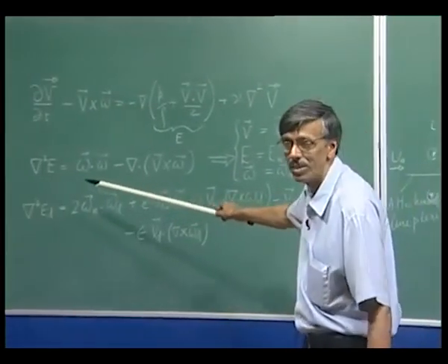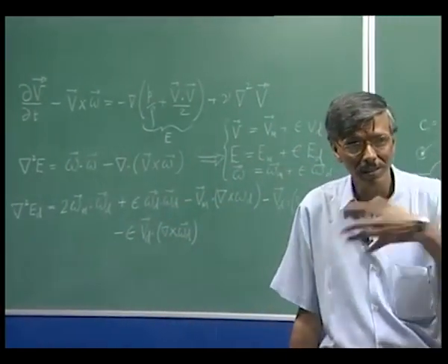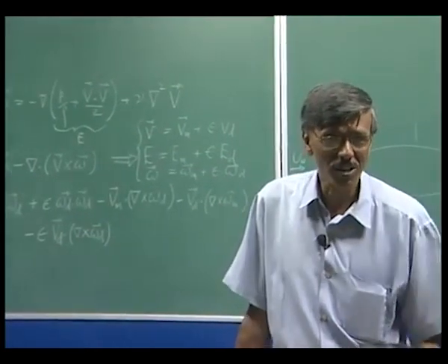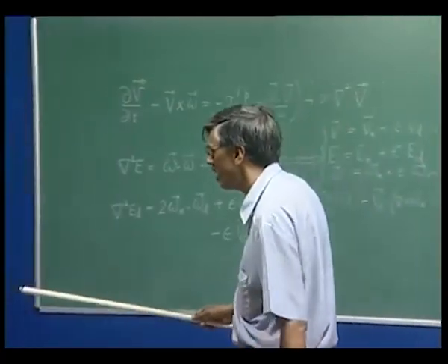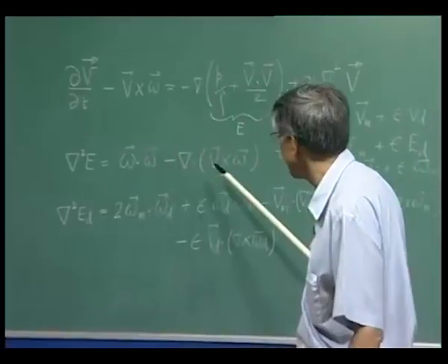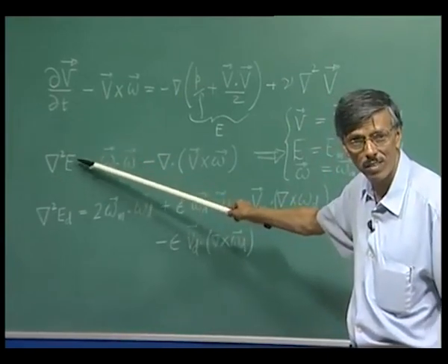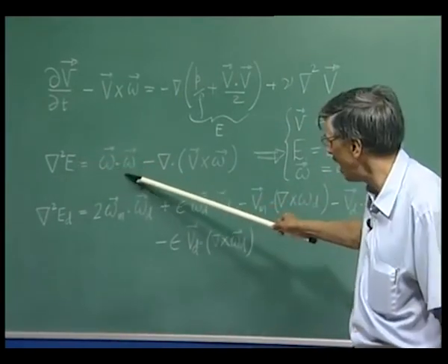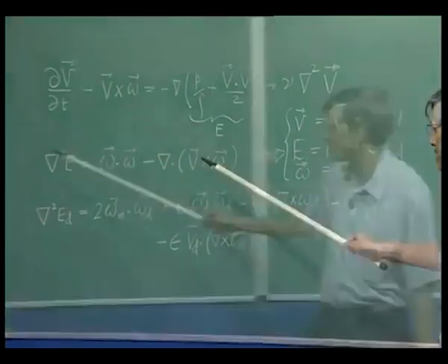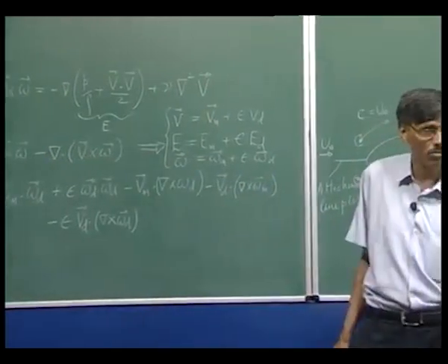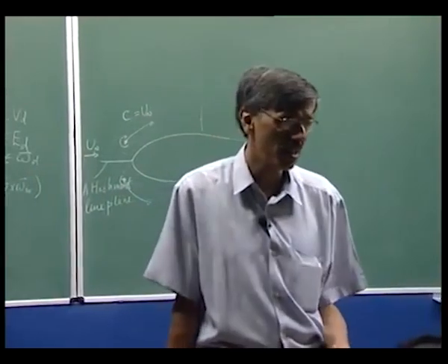However, when we take the divergence of this equation to get this, we do get the irrotational part that contributes to it, right. So, that is what we are saying, that this equation is interesting, because on this side maybe what resides is the irrotational part of the field, and this side we can very clearly see the presence of the vorticity vector, as well as taking this cross product of velocity times the vorticity gives higher order rotational effects.